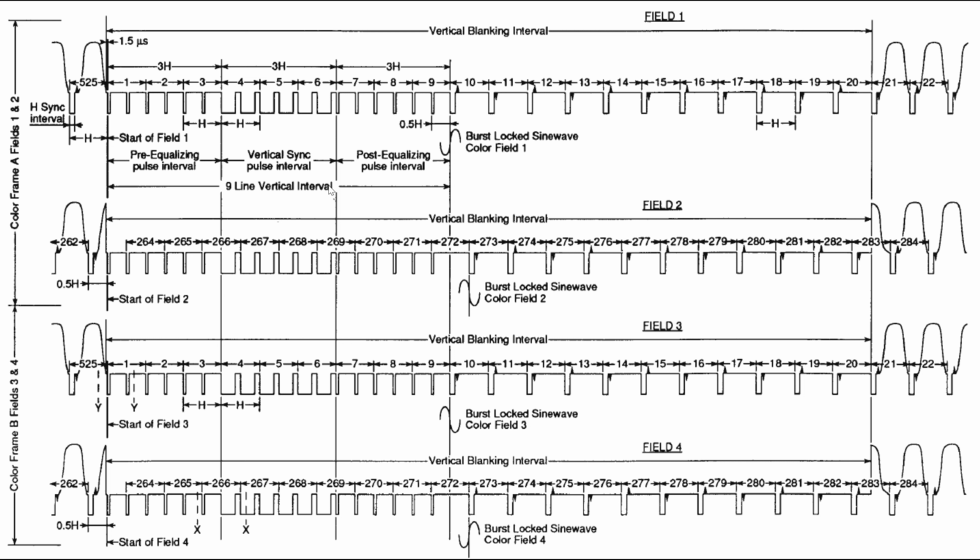So we have to pay attention to this stuff here and generate these pulses here. And I'm not going to get into it, but you can look up the spec on how wide these pulses are. And these are the vertical sync pulses, and there's 2 per line until it gets to here. And then this section goes up through line 20. And this is where the video information starts.